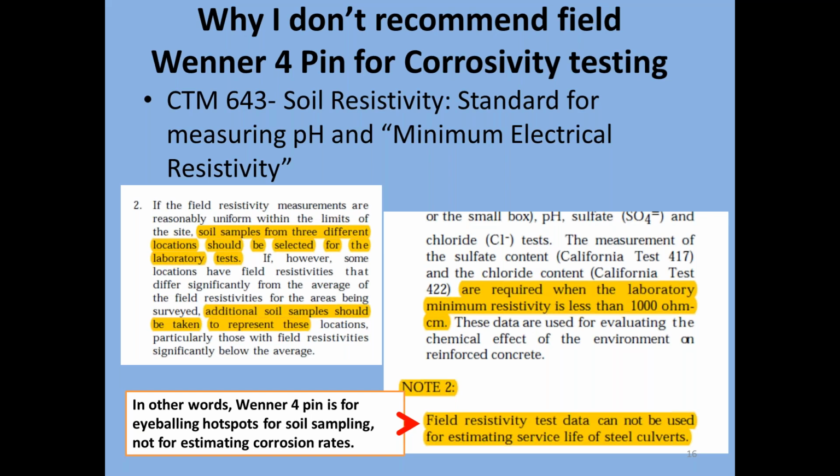Because you have to think, when you go out there, the soil may be very dry. Remember, in our laboratory, we test soil samples in a soil box as received and then as minimum resistivity. Very often, the as received is very dry already, and it's just extremely high in soil resistivity, ohm centimeter. But once you add a little bit of water to it, get it up to 20% moisture content or so, then it falls dramatically.